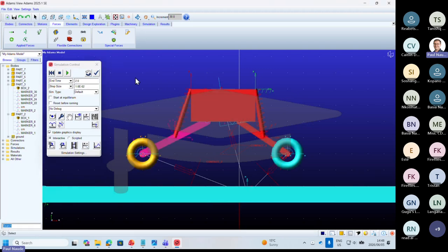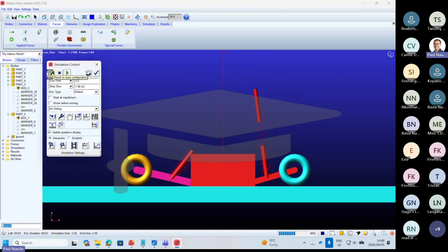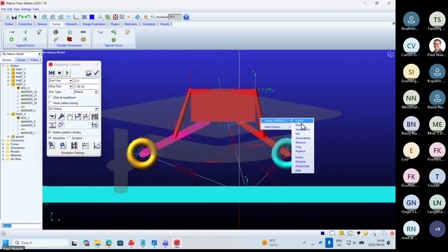All right, and of course, I want to see if that made any effect at all. Well, first thing that I can see is I've clearly connected this spring to the ground, to the pegboard instead of the body. So that's a no-no. So let's delete that.